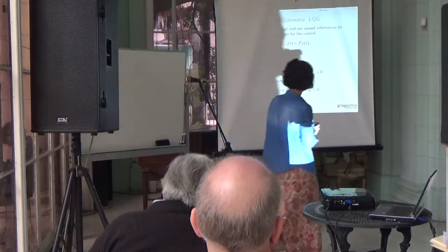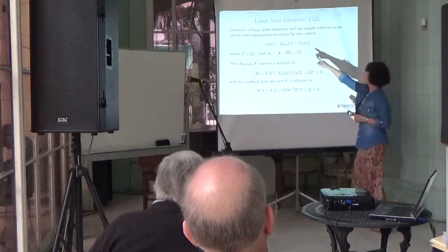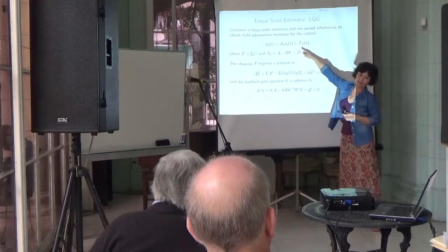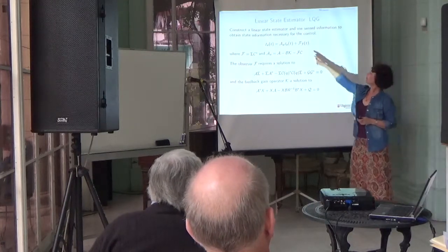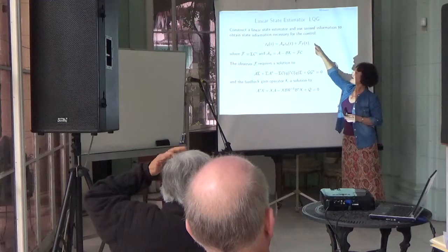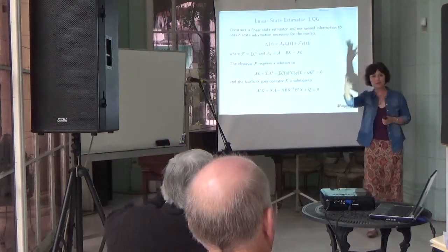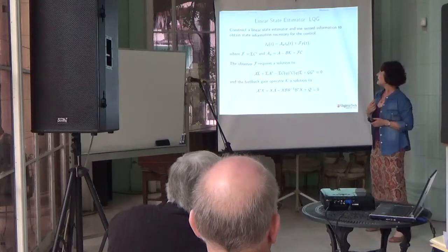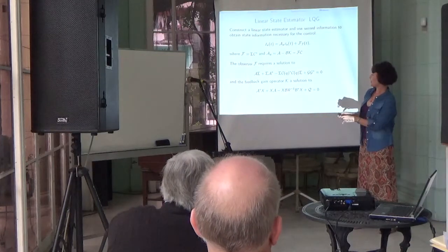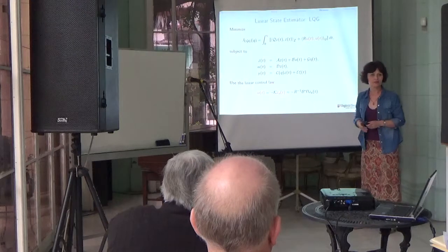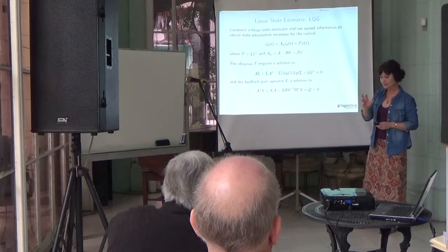So the idea is I determine these operators, A estimate and F, the input operator. I have my measurement Y. I want to figure out what the state estimate is. Z of E is an approximation for the real state. And once I have that, I will use that to construct the control. So that's the additional part of sensing.